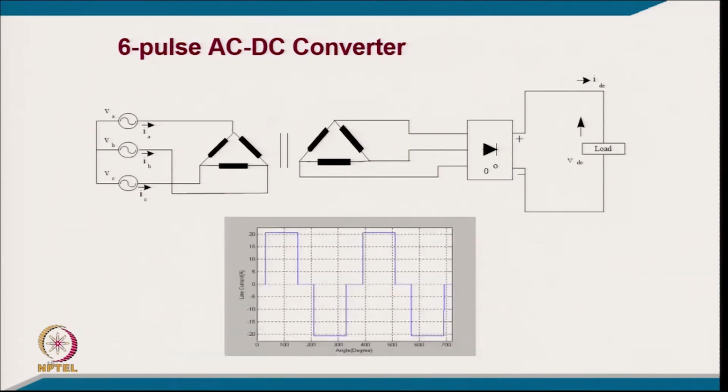So, this is related to a 6 pulse converter from 3 phase to 3 phase with transformer isolation. So, we have 1 converter and you will get this kind of quasi-square wave. You do not have triplen harmonics because of the 3 phase. So, the lowest will be the 5th and 7th, then the second band will be the 11th and 13th. But the important part is that because of the stepped waveform closer to a square wave, whatever harmonics are there, they are of magnitude fundamental divided by the order of the harmonic. So, if the 5th is there, that will be 1/5 of the fundamental current, the 7th will be 1/7. So, in this multipulse case, some harmonics are eliminated and the remaining harmonics are also reduced. That is the advantage of this multipulse converter.